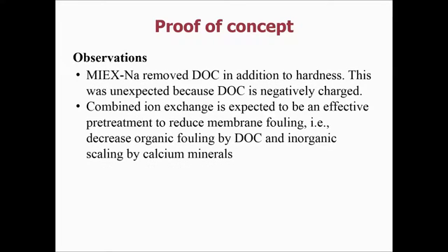Some observations moving forward. One observation was that the cation exchange resin, I didn't emphasize it earlier, but you might have noticed in the figure, the cation exchange resin removes some DOC. And that's not something we would expect. The cation exchange resin is designed to remove things like hardness. So why was it removing DOC? That was an interesting science question for us to pursue. And then we also thought that there could be some other interesting applications of combined ion exchange, such as thinking about it as a pre-treatment of membranes, because you're going to be able to, again with this single process, reduce both organic fouling and inorganic scaling of the membranes.